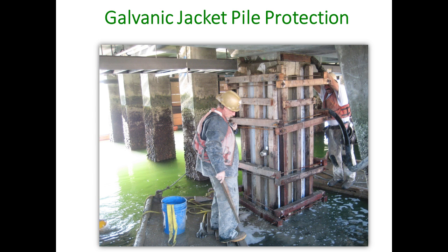And so this was just a mock-up of a jacket. And here's one that's actually being poured. And you can see the hose, the guy's pumping in. And so typically they're going to start from the bottom, and they're going to move the hose up as they go, and they're going to tremie it. And some of these jackets can be below water, and they're going to tremie it, and the water's just going to come out of the top of the jacket. And once the jacket's full, they'll stop pumping and move on to the next jacket.